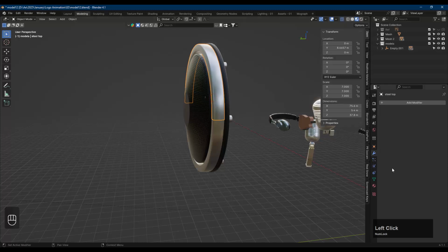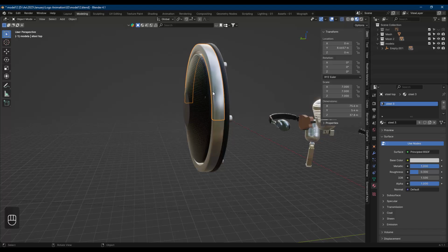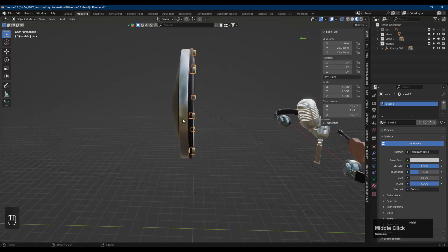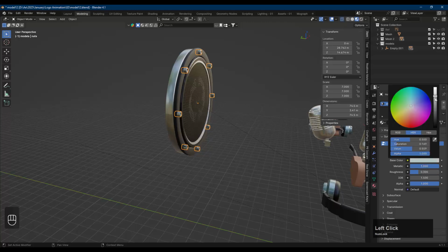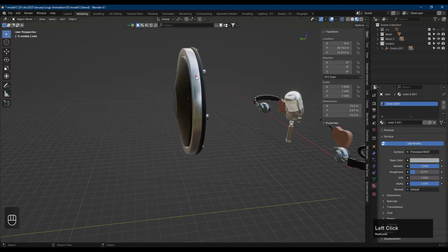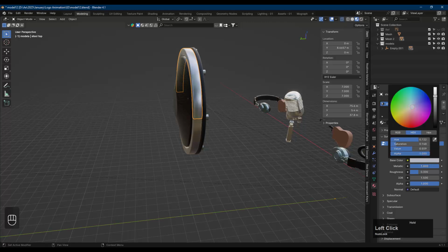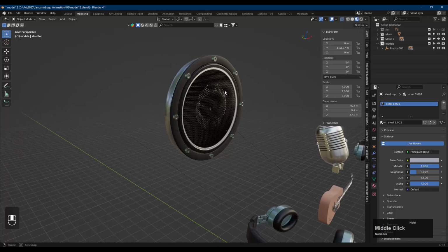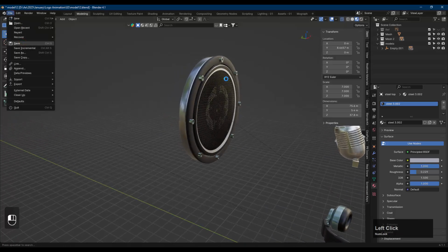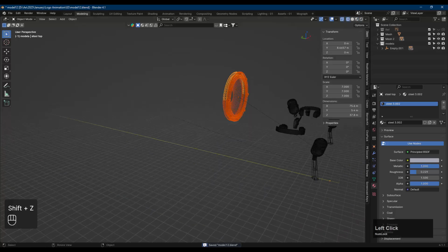Maybe let's try to apply a different material so that the element can differentiate. All these three has the same material, so that's why element has confused. Let's select this and then let's use this option, which will duplicate the exact material and apply another name. Also just change the settings a little bit so it can be actually different textures. So hopefully this will work properly now. Just press Shift Z and select these and then export.